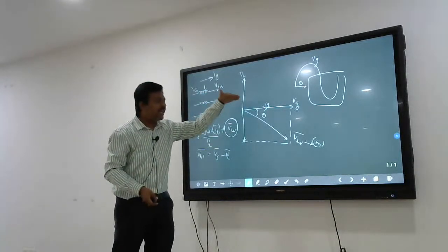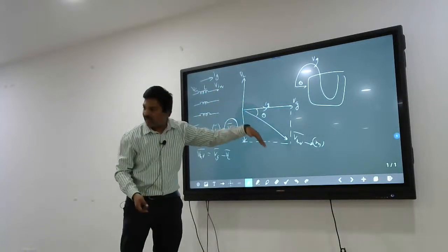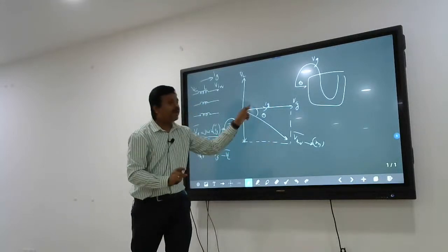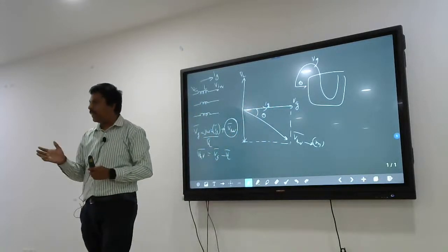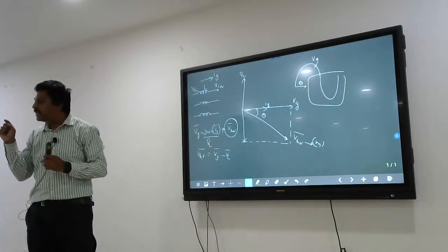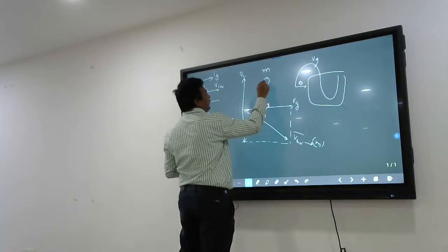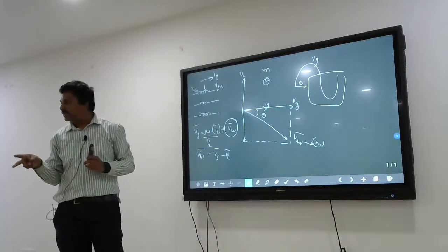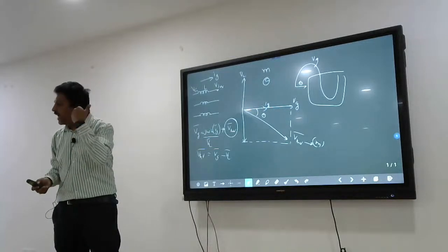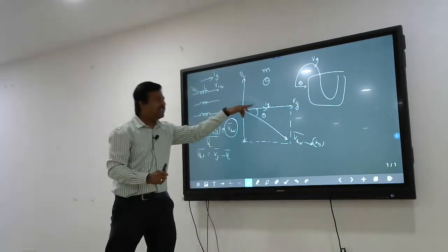So we take Vg and Ig in phase. We are assuming that Vg and Ig are in phase, and we are identifying the V inverter direction. Once you give the PWM like this, you will get the Ig like this. Are you getting the point? First we need to decide the modulation index. So the deciding parameters are the modulation index and theta. These are the two deciding parameters. But how do you decide M and theta if you want to transfer reactive power or active power? Imagine I want to transfer only active power, then Ig should be in this direction.